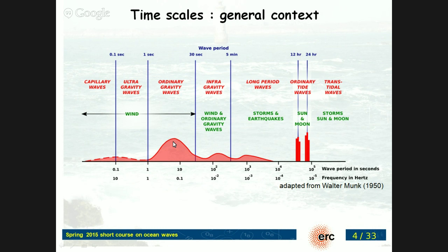But then what I will discuss a bit more is this interesting region of what's called long waves or infragravity waves, which have typical periods between, say, 30 seconds to a couple of minutes, and actually dominate the records of surface oscillations when you look at periods between 30 and 300 seconds.